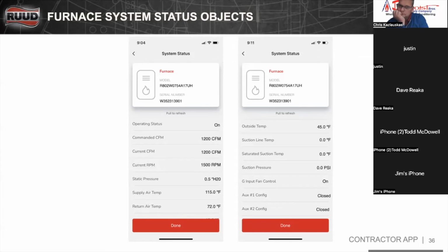Currently, it is only in the 96V and the mods. And you're going to need a return and a supply sensor on air handlers, because if they embed that in the board, you're pulling through the coil, so you're not getting true return air. So air handlers are going to be accessories for that. Furnaces, down into the 95T or whatever will use this app, will also have that sensor embedded in the control board.